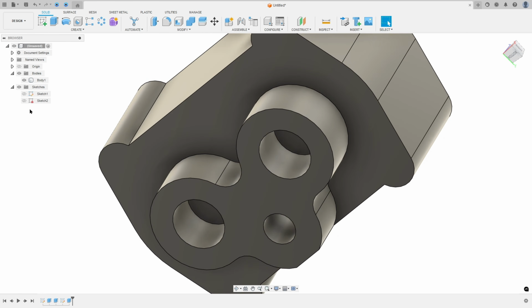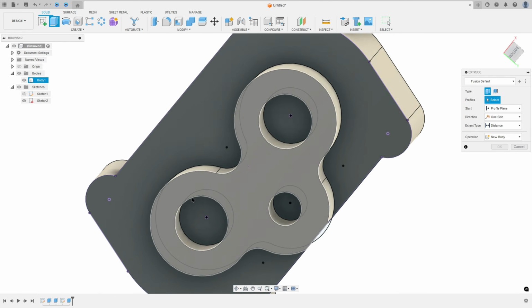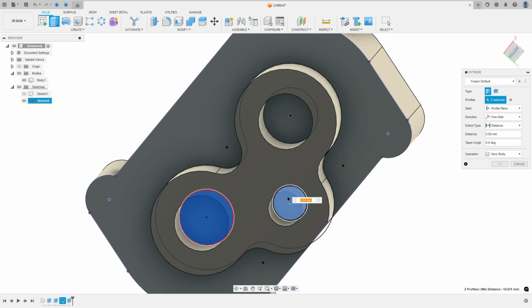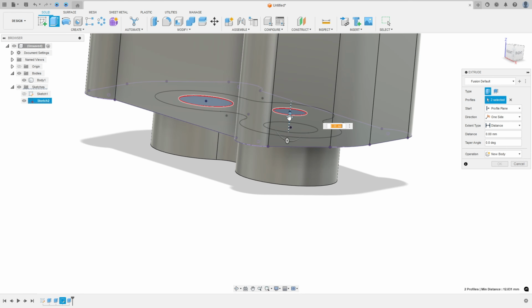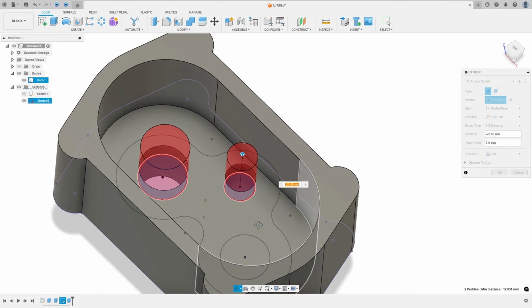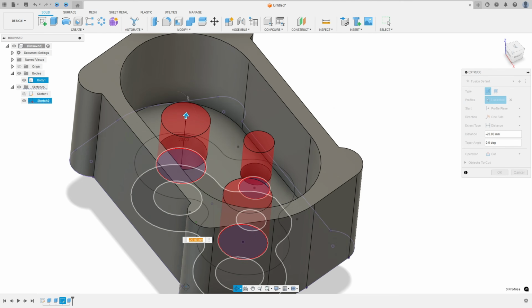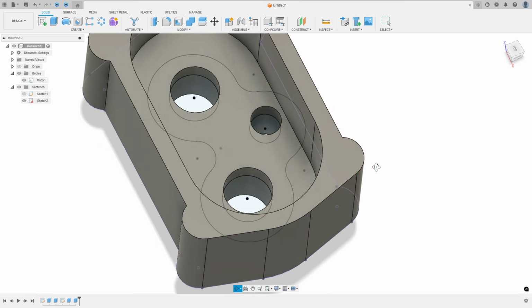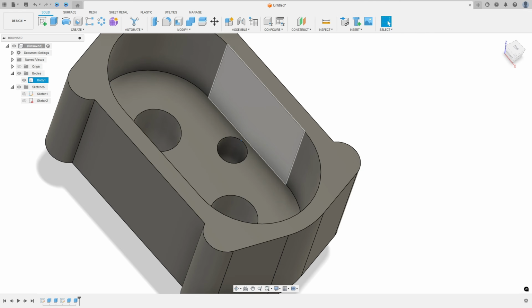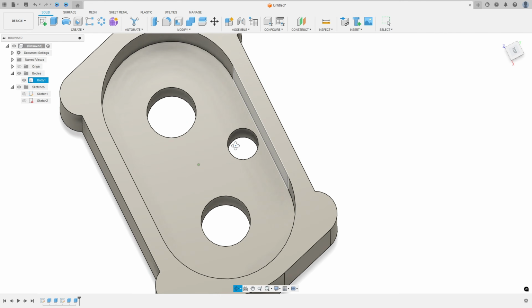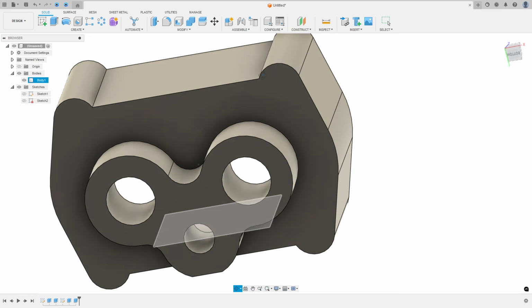We made this. And here we can show the sketch tool again, go to Extrude and select these 3 circles and make a cut here to this side, minus 20 millimeters. Select all the circles, okay? All these 3 circles here. And press OK, operation cut. Hide the sketch tool. We made this. Okay.